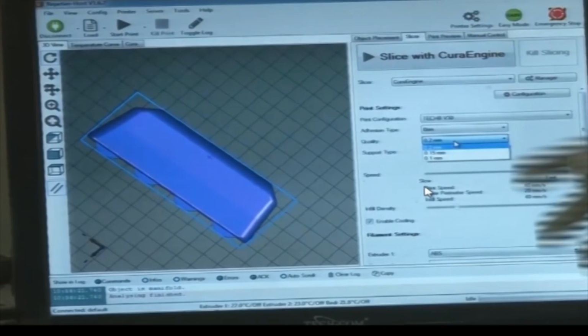And also, as I said, the quality and speed are countering each other. If the quality is higher, the speed would be lower, because between 0.1 mm and 0.2 mm, obviously the speed would be 50% of 0.2 if I use 0.1, okay, because 50% of the layer size is being deposited at each layer, at each slice.